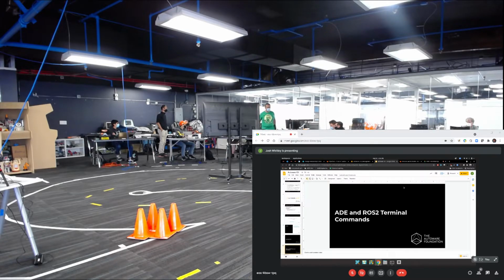When we're running it, are you running native or are you pushing Docker? It has to be with Docker, unfortunately, because it's using ROS Foxy, which is 20.04, and the image only supports 18.04 for Jetson. So we can do it. Literally just pull it.